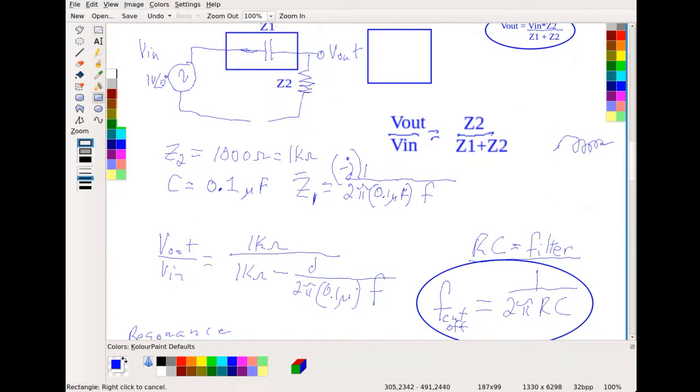So we're looking at this box, and what is going into the box and what is going out. And Thevenin, if you remember, just gives you series impedance. So Thevenin doesn't really work in there. You've got to calculate this V out piece, so you're looking at a voltage divider. So I guess no, we can't really do Thevenins there.